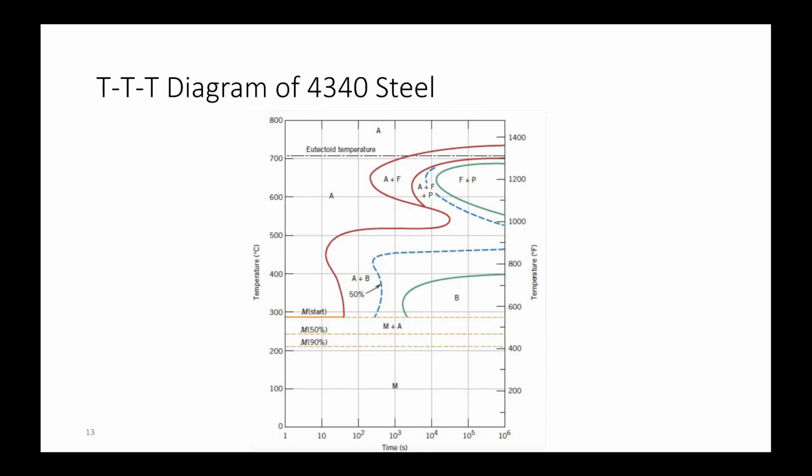But if you are adding small interstitial atoms, then there are chances of formation of intermediate compounds. These compounds will form, so there won't be 100% solubility because of the formation of these compounds. So it's actually due to that size difference, which should be very small. If two atoms sit side by side in the periodic table, they are more likely to form an isomorphous system.